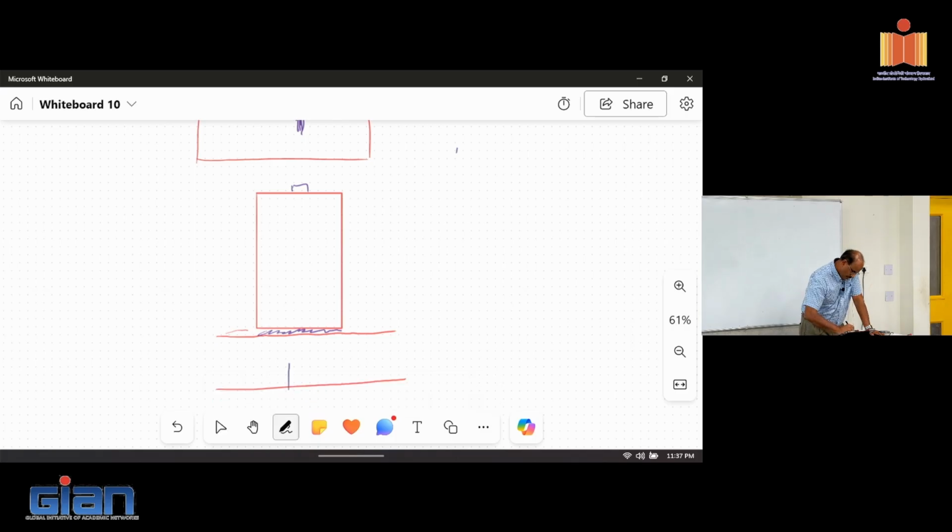So there's a tendon that goes in there and holds the walls together. And I make sure this is unbonded. Let's assume for now that's what we're going to do. It's held only at the end. So it's like putting a long rubber band made out of steel, right?